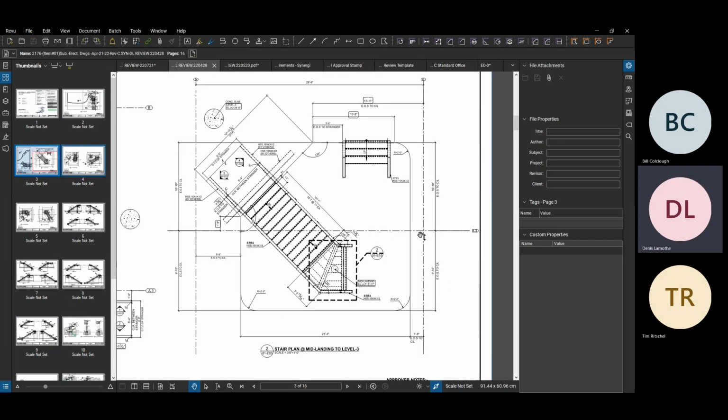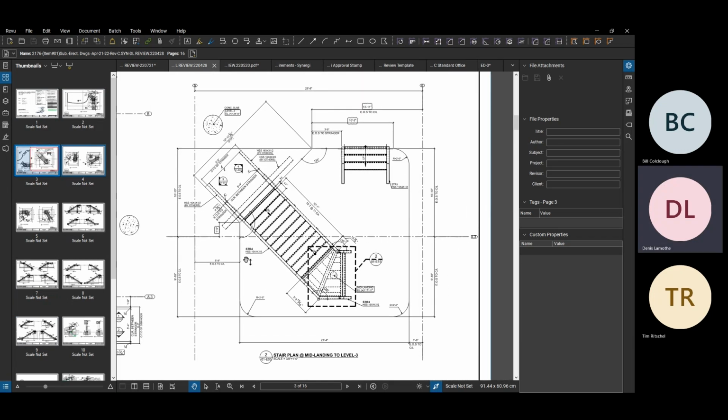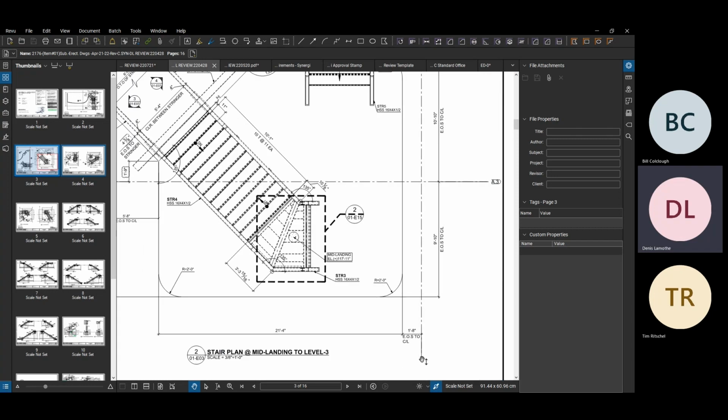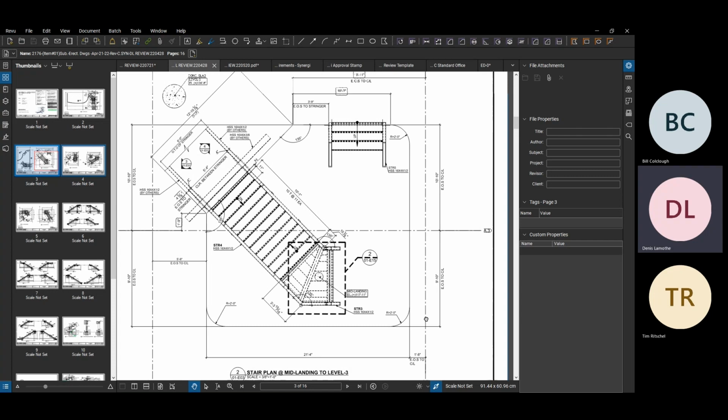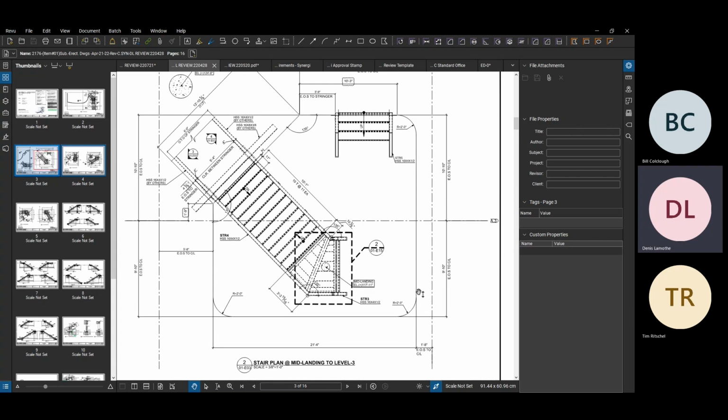We'll also want to check any openings in the floor slab, whether it's for installing our stairs up against or for future installation of our guardrails. We want to check that the dimension of the floor slab opening matches what we've surveyed. If we don't have survey information, it should match what's on the architecturals, and the pertinent dimensions, especially to a control line or a grid line, should also be included. This helps the installers double check things before they install.